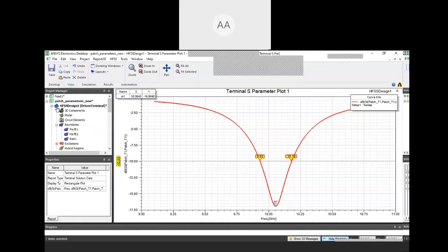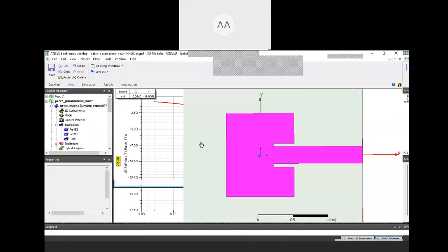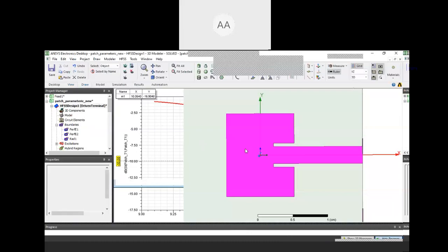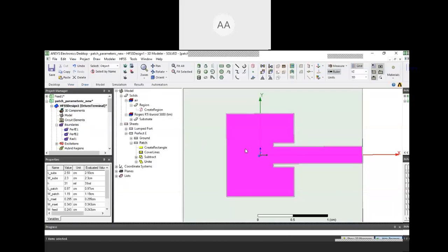But why I'm saying it is not meaningful is because if you actually generate the equivalent circuit, the first step is to divide this structure into smaller components. This structure can be divided into, let's say, two parts: the microstrip line feed, and the patch. The second step is to do an analytical study of how to model a microstrip line. In that case, you will be able to generate an equivalent circuit of a microstrip line.